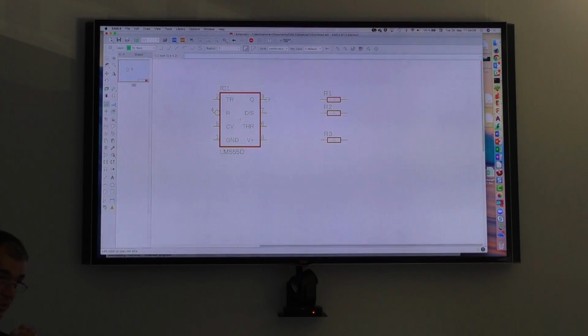In early versions this was not so obvious, and you had to take care of the grid setting. You see we have 0.1 inches as a default grid here. All the symbols we have there, all the pins we have there, are all placed in this 100 mil or 0.1 inch grid.